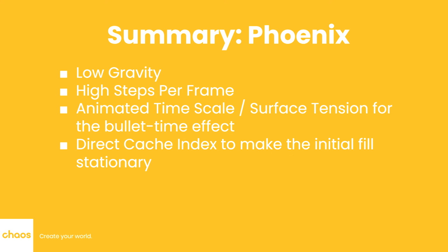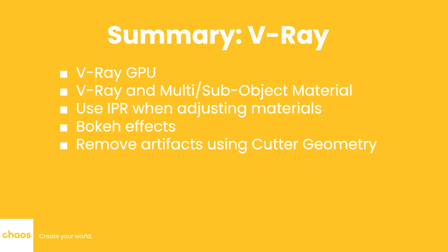In Phoenix, we optimize liquid flow by setting low gravity and SPF to 6, resulting in a smoother sheet of water. Bullet time is achieved through timescale animation, coupled with surface tension adjustments. For a steady liquid fill, we utilize the cache mode in the simulator's input and animate the value of the direct cache index. We use V-Ray GPU for the final render, and tyFlow particles received a multi-sub material for the glass cup, metal ball, and pearls.